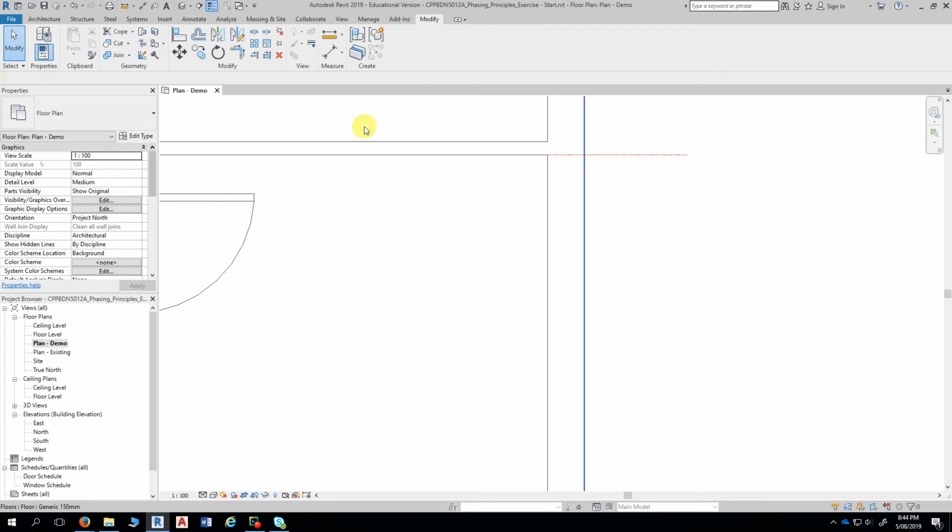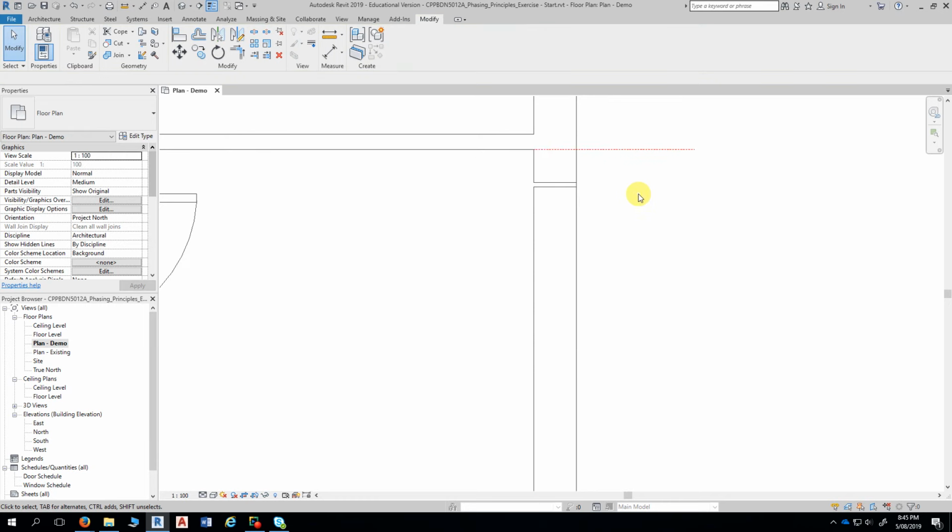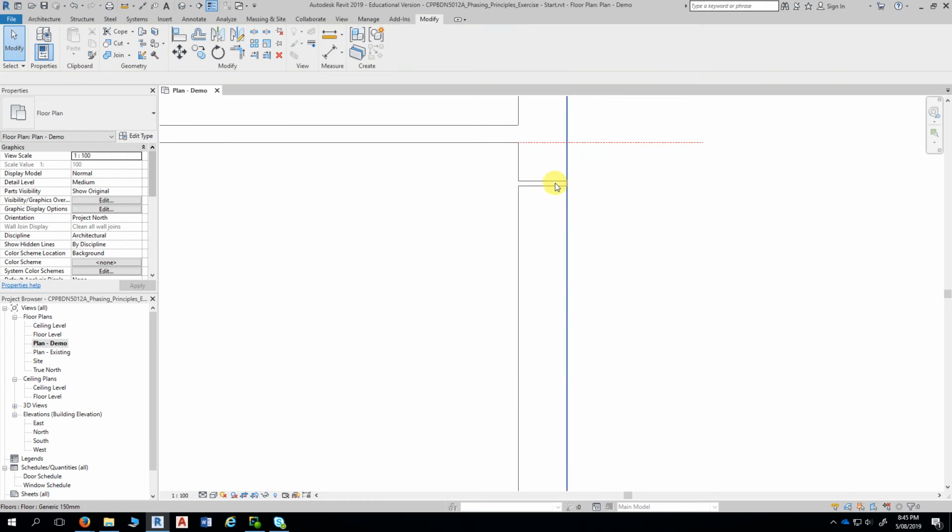Okay. So let's come back up to the other end of the wall, this end of the wall here. And what we need to do now is actually put a split with a gap through here, underneath. Hit the escape key a couple of times, reselect the wall, and unlock the gap. Unlock the gap. Okay, deselect, hit escape, and then take the wall end up to the reference plane in each case.